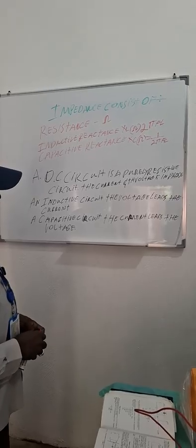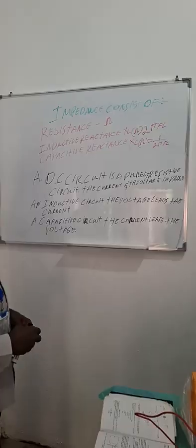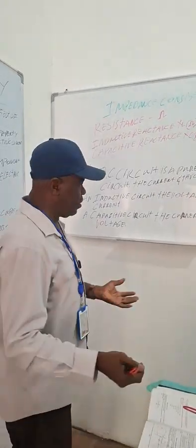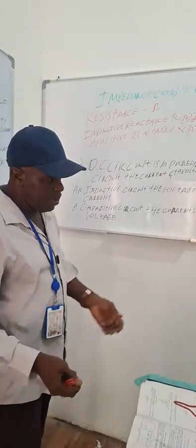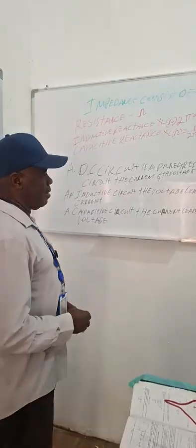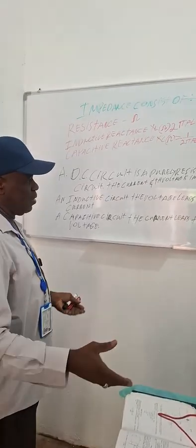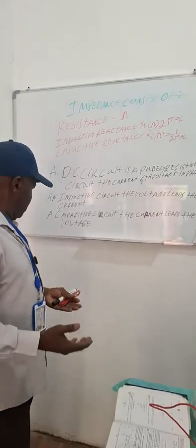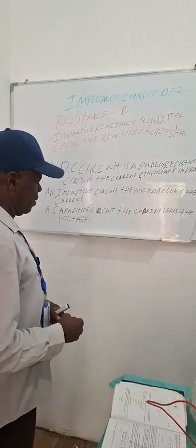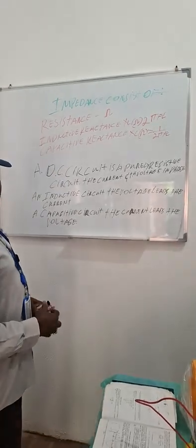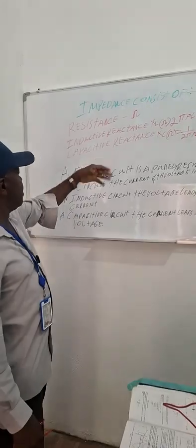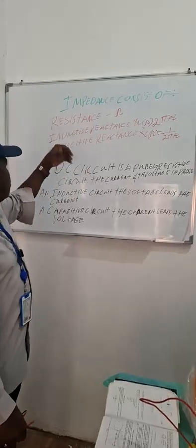In order to correct that anomaly, we normally use overexcited synchronous motors, right? And you can also have a bank of capacitors connected to the terminals of the motors, which is made to adjust to the correct power factor, right? So remember, in the AC circuit, as I said, impedance consists of resistance measured in ohms,